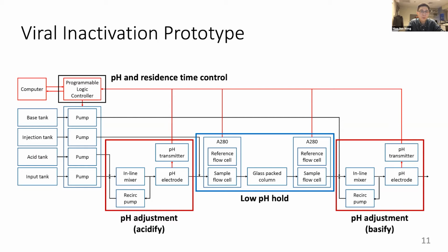And the programmable logic controller was used for the low-level control of the overall system. Measurement data were received from the pH and the UV sensors, and the multi-channel peristaltic pump was connected for control actuation. The programmable logic controller was also connected to a computer for data collection, human-machine interface, and online parameter estimation.